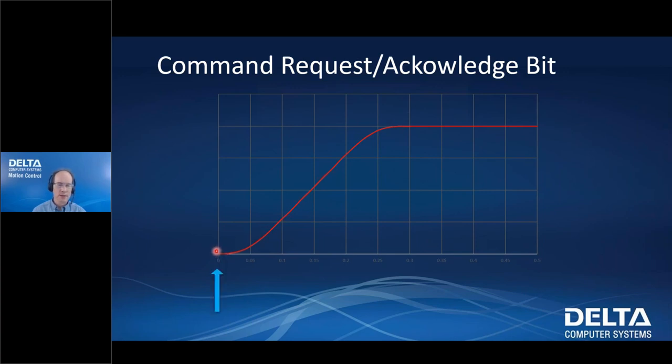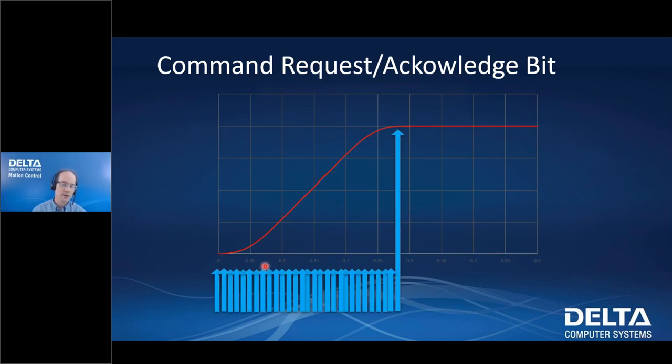So we send the command at this time, and then the PLC needs to wait for the in position bit to turn on so it knows the command completed, so it knows to go on. And so what the PLC does is after it sends this initial command, it does a bunch of checking of the in position status bit that is hopefully continually reading from the RMC. And when that in position status bit turns on, then it knows to proceed.